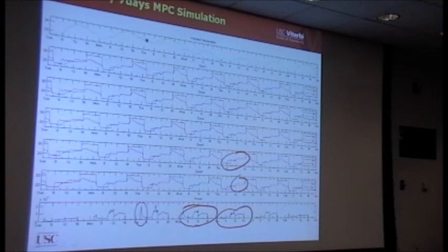So within that, the first half has a lower temperature, but still within the comfort zone. And this afternoon, then the temperature gets gradually to the higher end of the zone. And after 6 o'clock, you pretty much change the set point to the high value, and the air conditioning is effectively shut down. Okay, so that's how the result is turning out.